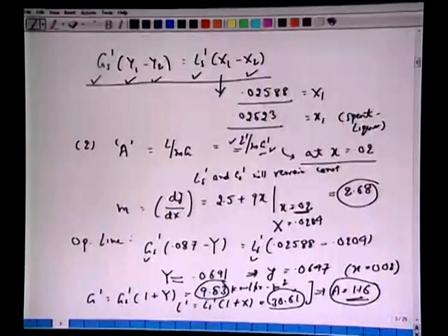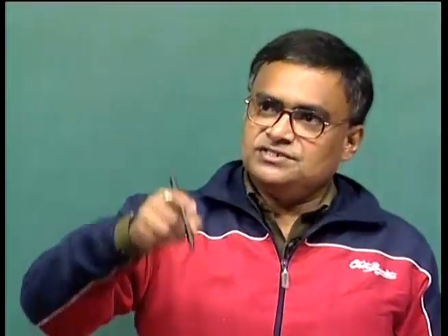All right. And the last part, the question is calculate the gas film based driving force. So, that is your Y minus Yi. Now, again the driving force in the column, if you recall, it changes because the mole fraction Y changes, so Yi, the interfacial concentration, also changes.